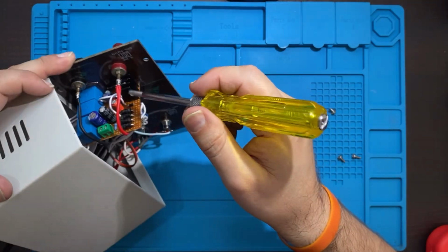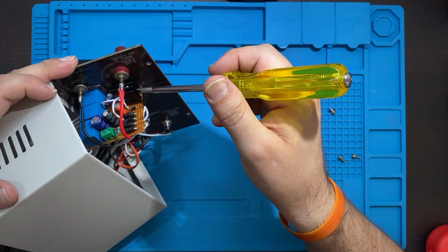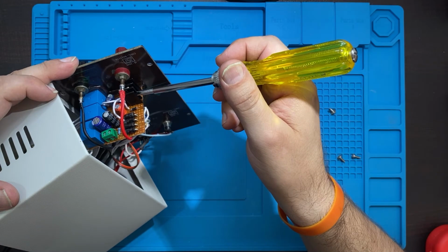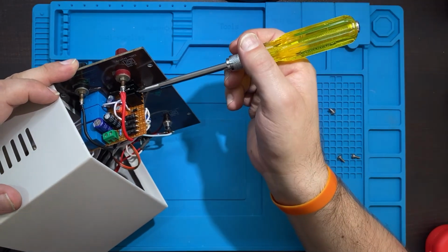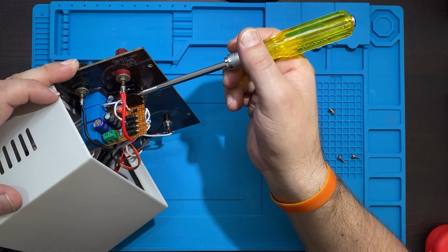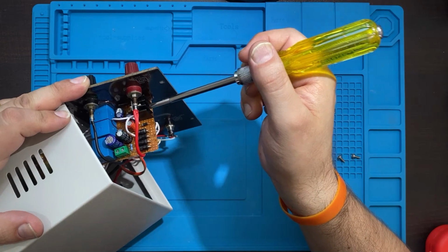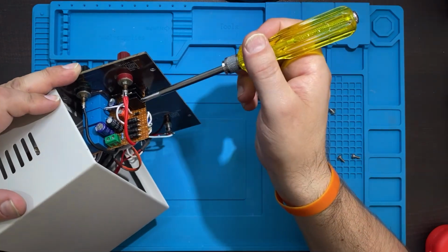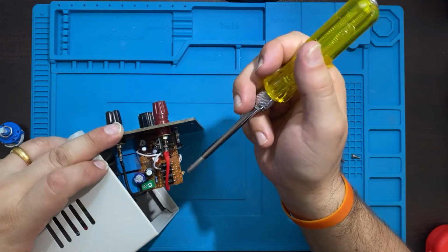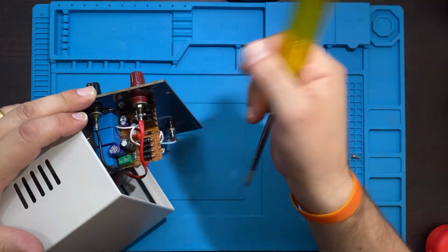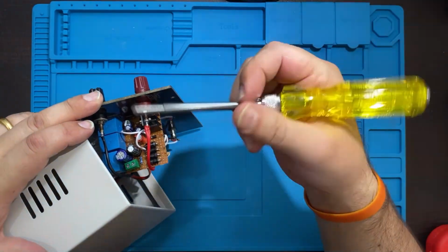So here's the LM338. As you can see, there's a fairly small heatsink, and I haven't actually loaded everything, especially the 6 volt setting with 2 amps, but it doesn't heat as much as it would with 40 watts anyway. So this is smaller. Maybe I need to put a bigger one later, when I can actually load it with 2 amps on every voltage, and I can check that.